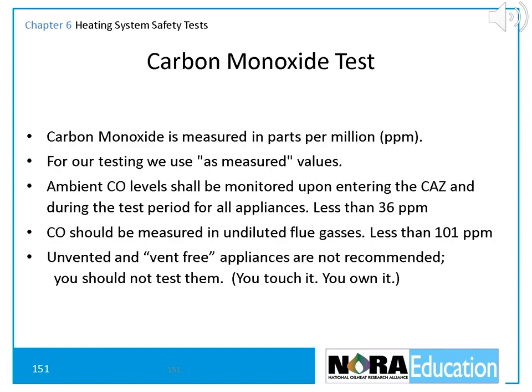They also measure CO in undiluted flue gases, the gases in the heat exchanger before the draft relief air or the draft regulator air is blended with the combustion gases. The reading for the undiluted flue gases at steady state should not be higher than 100 parts per million.